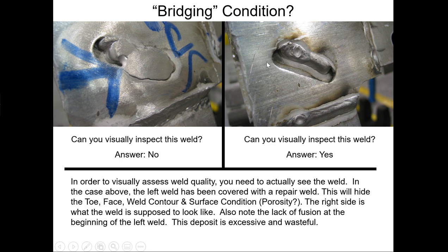Now, what they had was what was over here on the right. That's what they started off with, and it probably had some problems. So they just went and welded it up. But it's not even a fillet weld anywhere. My point from this slide is this: the weld needs to be what they asked for. If it's anything other than that, it's not sufficient. Even if you think it's more, there's no such thing as more. If I give them more, it's better? Don't think like that in welding. More is not better. More can cause us more problems than you can imagine.